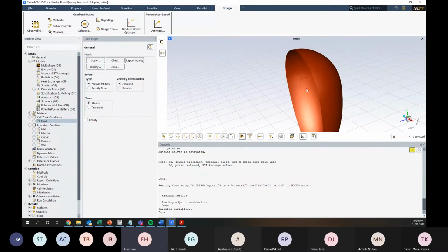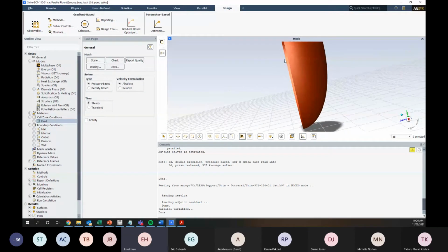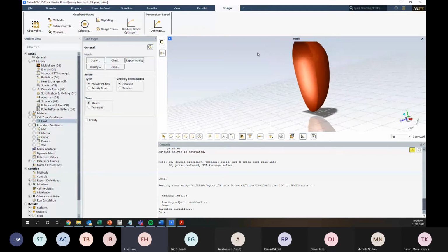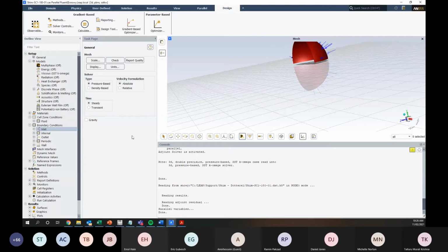So basically changing the shape to be this egg shape, this whole outlet here has less reverse flow, because obviously the flow is coming down from the inlet, and then the propeller is spinning and forcing that flow down further. So changing the shape reduced the amount of backflow and allowed us to get a more stable solution.